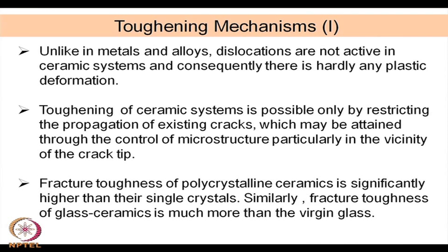However, as just mentioned, dislocation movements are not of that importance in fracture of ceramics. It is actually beyond the dislocation movement. It is a sudden fracture, or the cracks already get generated in the material, and it is the propagation of the crack which has to be restricted if the ceramics have to be strengthened further.